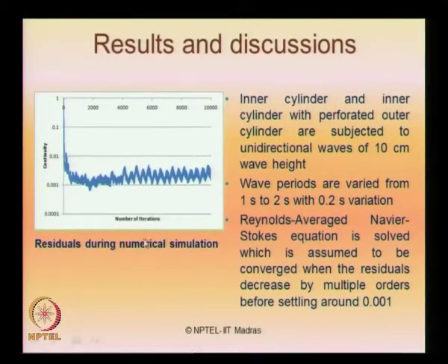If you look at the residuals which are arrived from the numerical simulation, which is used as one of the check measures to see whether the results have converged, the inner cylinder and inner cylinder with perforated cover are subjected to unidirectional wave. Wave periods are varied. Reynolds average Navier-Stokes equation is used and solved, converging with the residuals which decrease by multiple orders before settling around 0.001, as you see in this figure.